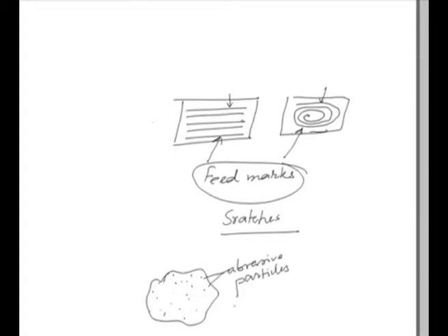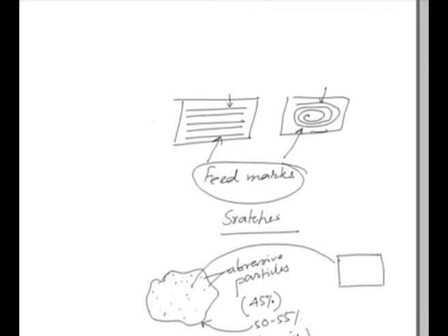Now, these abrasive particles are at some percentage, say for example 45%, and the remaining 50 to 55% is the carrier. This is also called the carrier. They are mixed together and made into a deformable stone. Now, this deformable stone, which is in fact flexible, can be made to pass through some restrictions, say for example a small hole like this, with a diameter of a few millimeters, say 10 millimeters or so. Now, this deformable stone can take the form of the feature